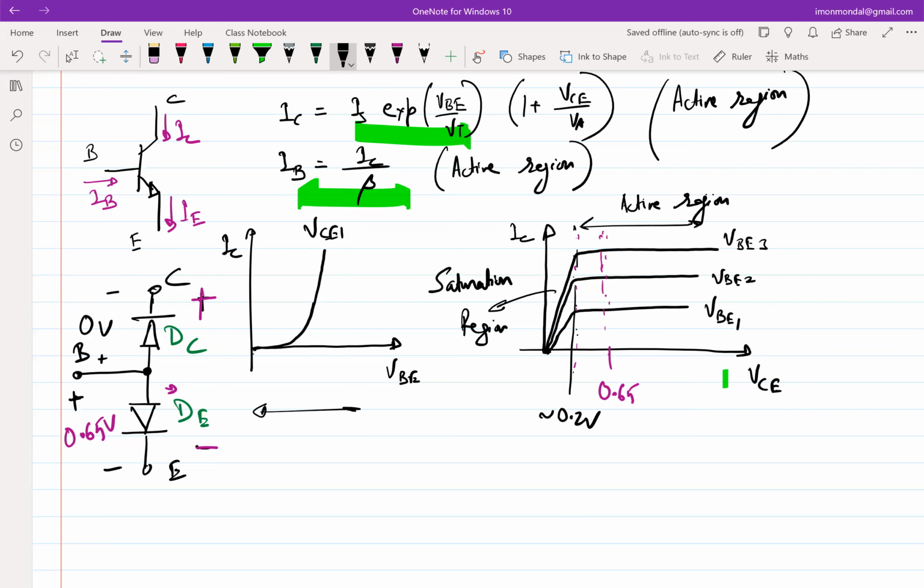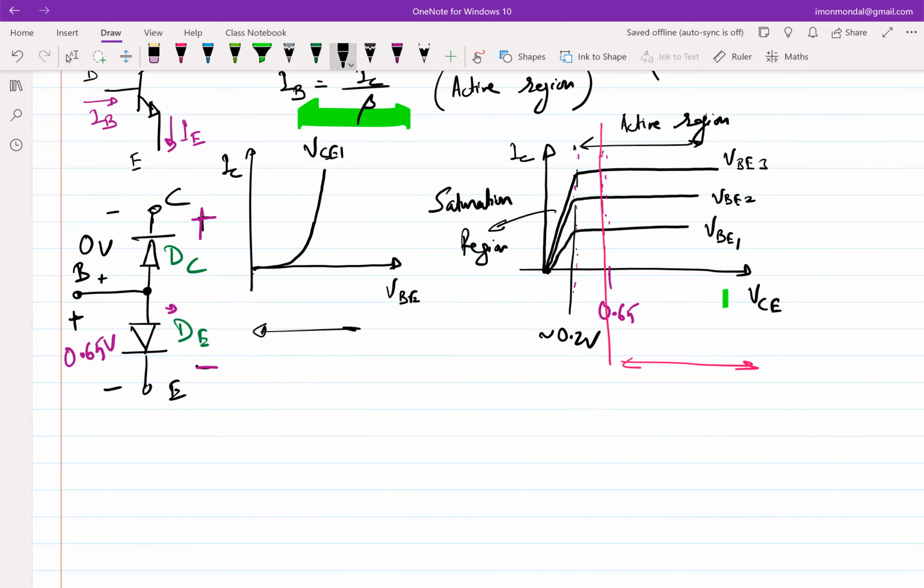But that is a matter of detail. We will not get into that. For us, as circuit designers, all we have to ensure is that we don't get into that murky zone of whether it is actually forward biased or not. So we have to make it fully reverse biased. We'll operate here. So in other words, we have to ensure that VCB min has to be 0. This will be important for your swing limit calculations, right? How low can a collector voltage go while keeping your BJT in proper operating conditions?